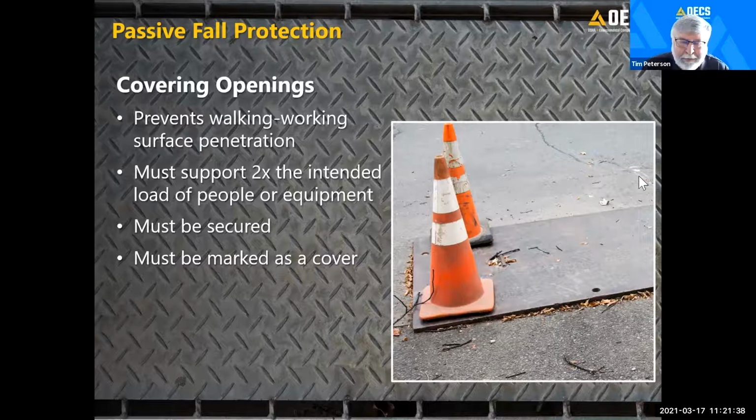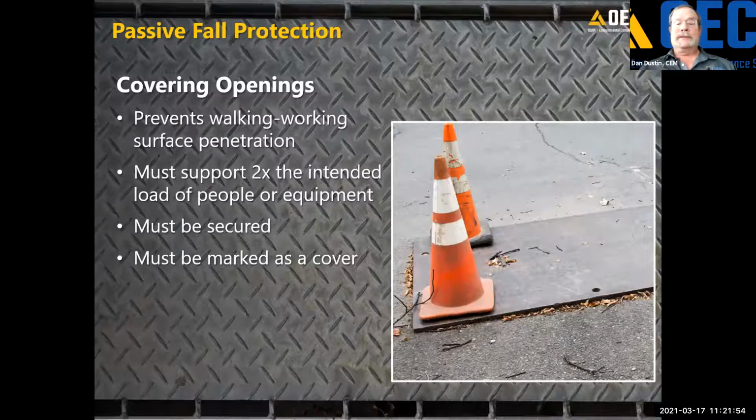Those of you that cross over into general industry, this requirement also falls under there for protecting floor openings and having them secured and marked with the word hole. Yep, they have to be secured to prevent displacement. Unfortunately, all too often, people will put down a cover. They won't mark it. They know the hole is there, and somebody else will come and take that piece of plywood to use it for something else. And now I've got an open hole in the floor. So they have to be secured against movement, and they have to be marked as hole or cover in a contrasting color to make it obvious what they're there for.